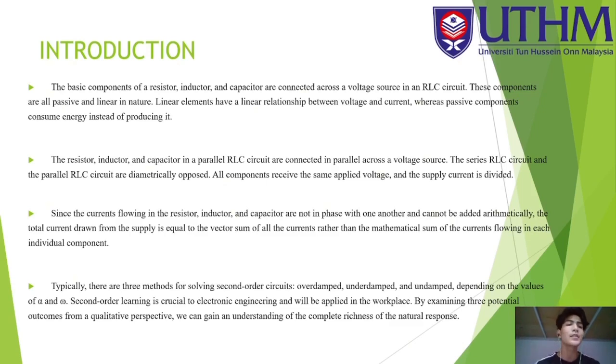Next, since the currents flowing in the resistor, inductor, and capacitor are not in phase with one another and cannot be added arithmetically, the total current drawn from the supply is equal to the vector sum of all the currents rather than the mathematical sum of the current flowing in each individual component.